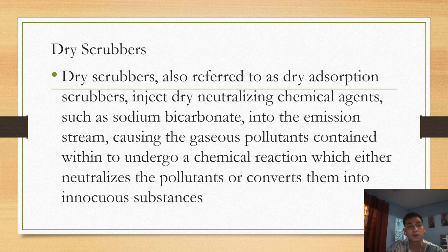Dry scrubbers. Dry scrubbers, also referred to as absorption or adsorption scrubbers, inject dry neutralizing chemical agents such as sodium bicarbonate into the emission stream, causing the gaseous pollutants contained within to undergo a chemical reaction which either neutralizes the pollutants or converts them into innocuous substances.